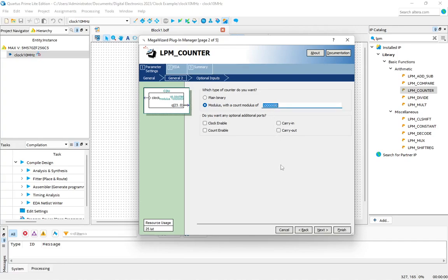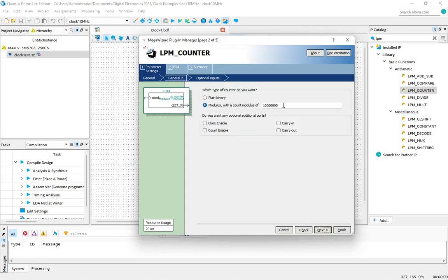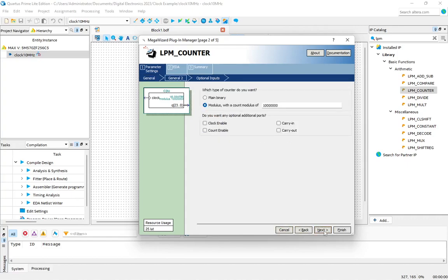And that can be stored with 24 bits. So just be careful here. You have to use 24 bits, and then you divide by 10 million to get that. The highest bit here will represent 1 second. I'll show you later how that works.